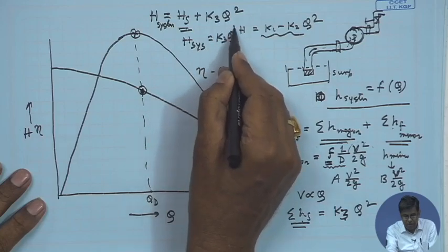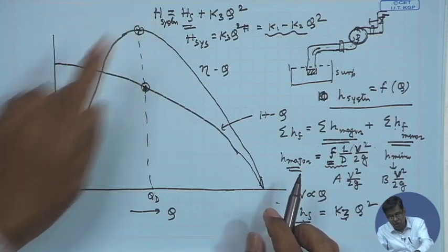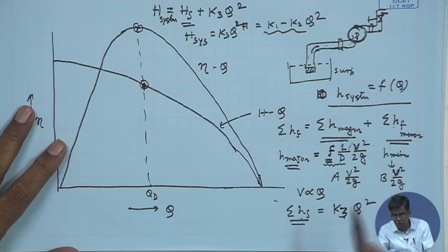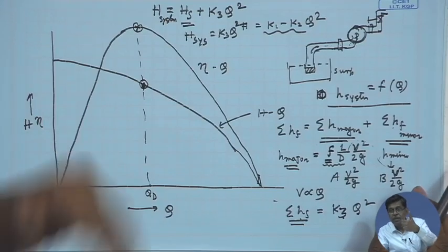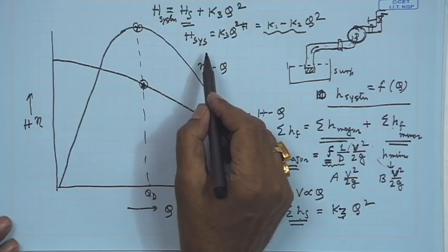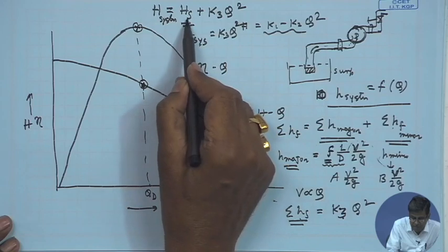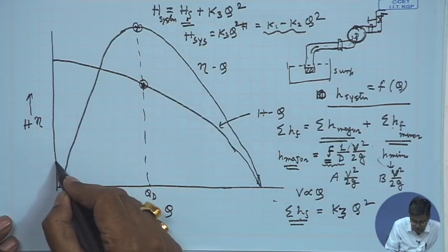That means the system will demand this type of head, so that this pump can be in operation to maintain the flow. It contains all the losses, and these minor losses also include the exit losses. That means the loss that is being incurred by the exit velocity head. So, if we consider this as the system resistance with static lift Hs, this can be shown like this.